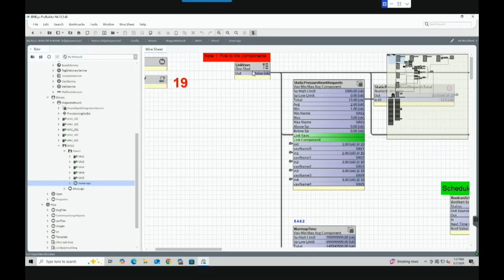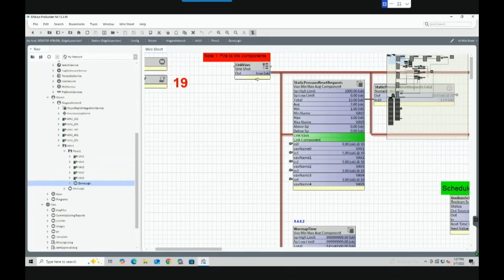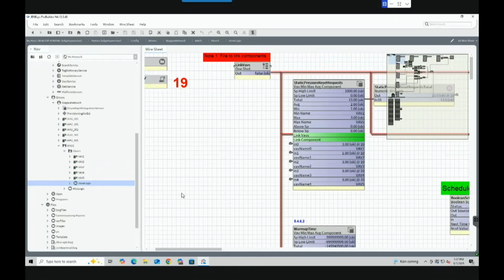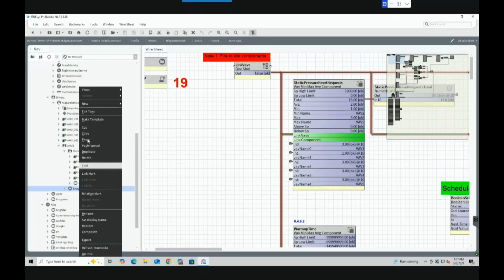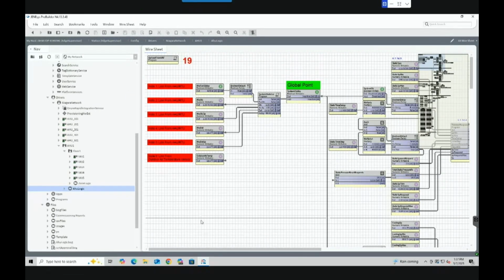Okay, well, let's go ahead and do that. So if I right-click Actions and go Link VAVs, what it'll do is actually go ahead and enable these min-max average components and tie in all the VAVs. So if I were to duplicate all these VAVs here, it would go ahead and add more VAV links if I wanted. And then, as far as the AHU logic folder goes, we can go to the AX wire sheet here, and we can see that things that we need to link to and from, we actually tell you to. So linking the fan status, set points, etc.